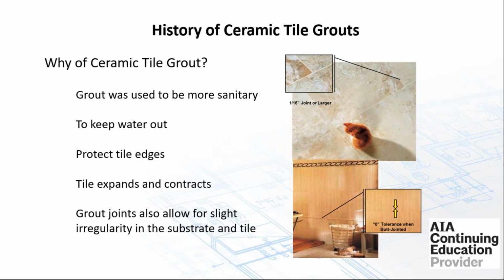So grout, why, of course, why ceramic tile grout? Grout is more than sanitary. It's designed to keep the water out. If you're just butting the tile, you of course would have water seeping through that. It's designed to protect the tile edges. Also, as tile expands and contracts, the grout is in there absorbing some of that movement. It's not a movement joint per se, but it does absorb some of the movement of the tile.